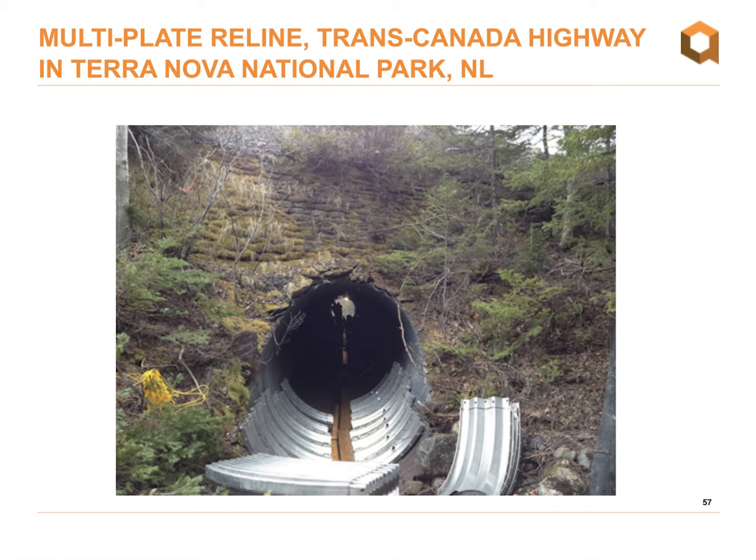Because of its location at the bottom of a steep embankment, accessibility to the existing structure was a challenge. The portability of the product made it a great solution for the unique geography of the site. And tunnel liner plate, which is only manufactured in Canada by Armtec, could be shipped to the site and hand carried in segments because they only weigh between 9 and 14 kilograms. These were brought through the structure just by hand. The alternative choice would have been to incur significant costs with building the access road to get down to the site.